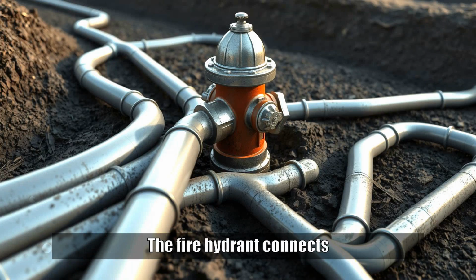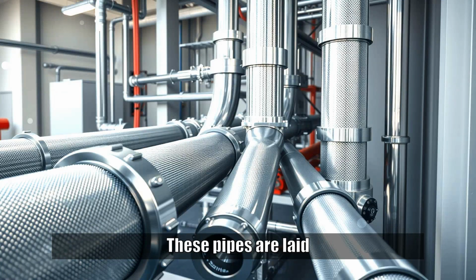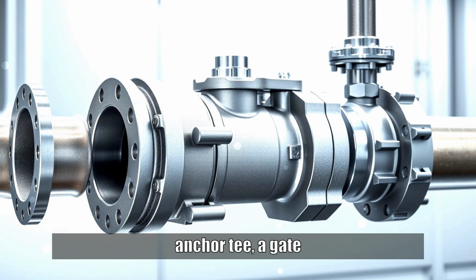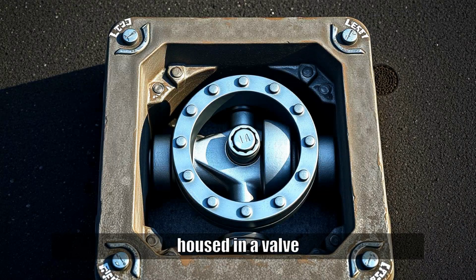The fire hydrant connects to an underground piping network, usually made of ductile iron (DI), PVC, or HDPE pipes, depending on pressure ratings and corrosion conditions. These pipes are laid from the municipal main or a dedicated fire water tank/pump system. The connection typically includes a mechanical T or anchor T, a gate valve, and a riser. The gate valve, often housed in a valve box, allows isolation of the hydrant for maintenance or repair.